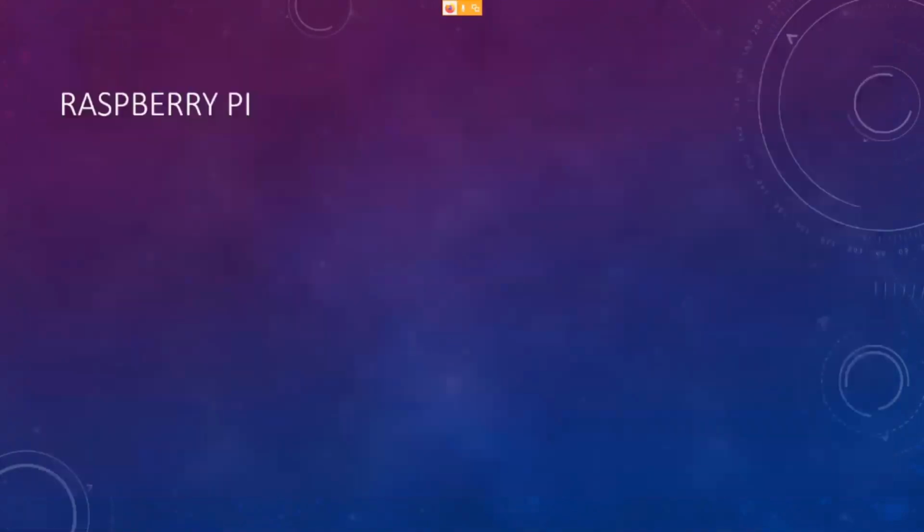So then on the Raspberry Pi side, the first thing we did was install software for the Botlink router. It allows ground control stations to upload missions to our flight controller. That just allows us, if we send a waypoint, the flight controller will be able to fly the drone to that waypoint. Basically, we had a map from our Android app through the Raspberry Pi into that flight controller. So it's just a 2-network process. And that is it for that part of the software.